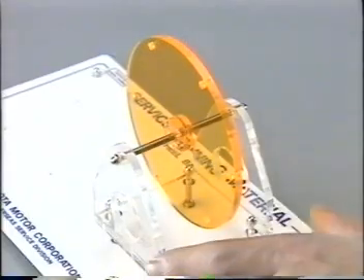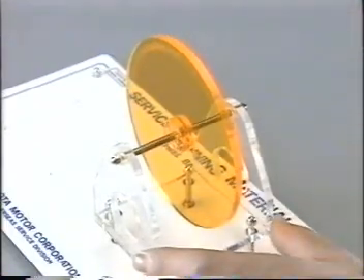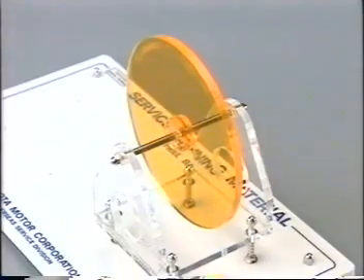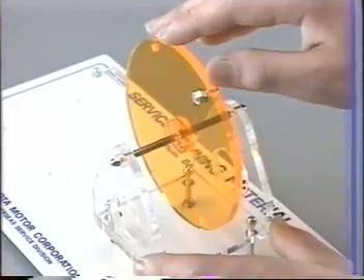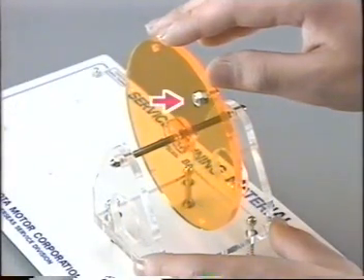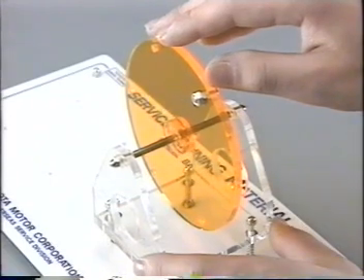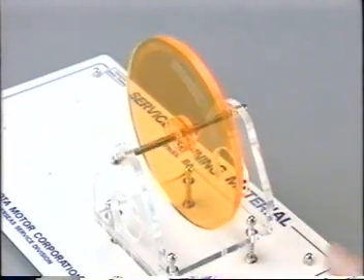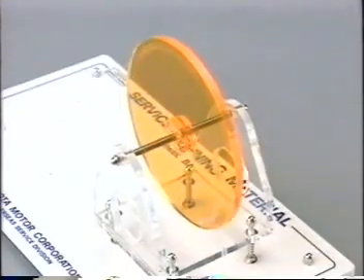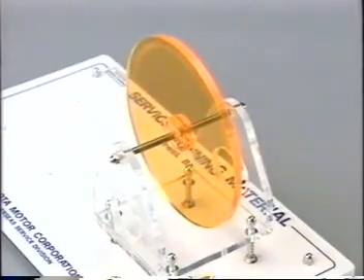Using this model, make a disc turn. In this case, it rotates smoothly because it is balanced. A particular point on the disc can stand still at any position. Now what happens if a weight is attached to a part of the disc? In this case, vibration is produced because the centrifugal force of the heavy part acts on the disc.